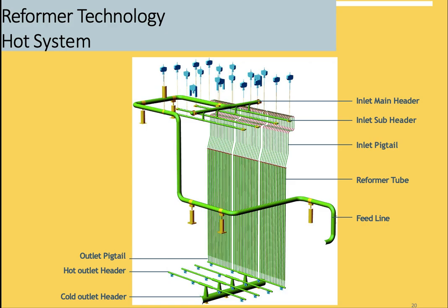Okay. What will you do if you remark a poor temperature profile along the tube? The symptom is very clear: cold inlet, hot outlet, imbalance, localized hot zones through the tubes, and reduced conversion. The root cause can be maldistribution of the feed for sure, channeling in the catalyst bed, and the inlet distributor may be damaged. The corrective action is to inspect feed distribution and reload the catalyst properly.